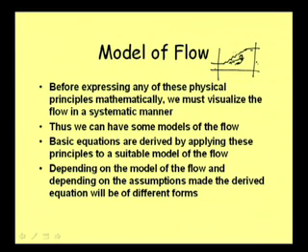If we go for the energy equation, because of turbulence a lot of energy loss is there, and we may not be in a position to fully understand how much energy is getting lost. So if we try to equate the energy here and here, this will be wrong. We will have to write energy here minus energy loss equal to energy here.